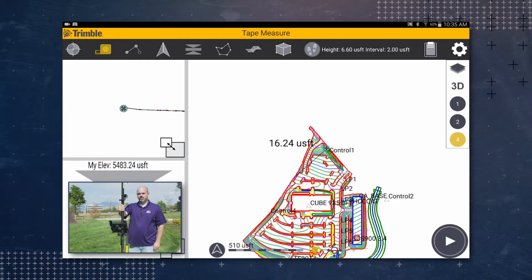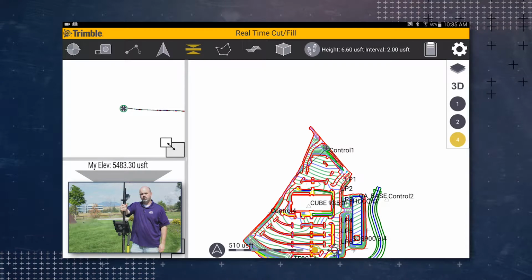Once the email has been sent, you'll notice that you're taken back to the map screen, and there's still a measurement in the center of the screen. This is the last measurement from the last point and all points from before that. You can choose to continue on in walking mode by tapping on the plus icon. You could then choose to tap on the tape measure icon, which resets the function and you're able to start a new measurement. Or you could tap the cut fill icon, which brings you back to default for the SitePulse software.